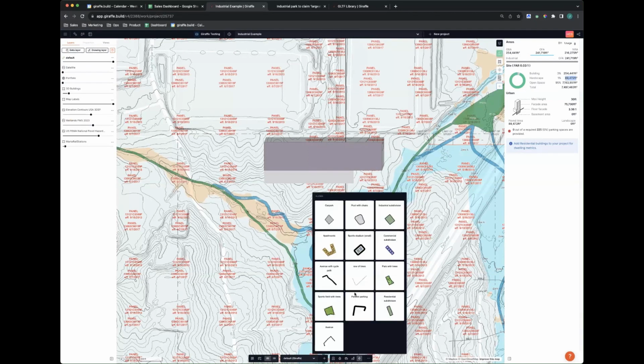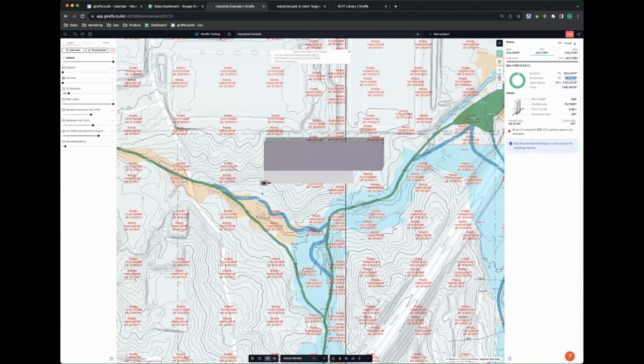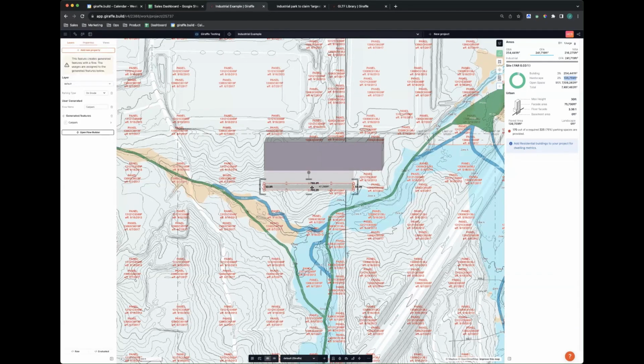I'm going to click on the lightning bolt, say car park, and trailer parking is about 60 feet from memory. If you're doing double stack, then maybe it's 120. We're going to go 60 for now, and we'll come the whole way across the apron. And you can see I'm holding S. When I hold S, I get center points of lines or edges. S is snap.